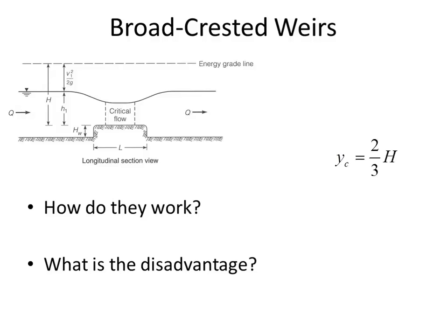On bridges, I noticed there's elevation markers. Are those used in some way like that, or is that just for height? They're usually trying to know what the stage is for flood control purposes, and they know that when the water level gets to a certain depth, somewhere along the banks, water will be flowing over. And so I think that usually they have a curve that relates stage to Q. You know, there is some curve, but it's not necessarily that there's a broad-crested weir at the bridge. They haven't installed a broad-crested weir. They have some other relationship that allows them to know Q versus that stage.